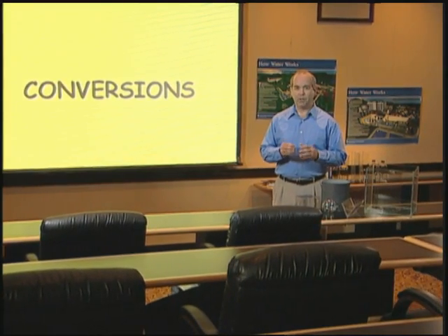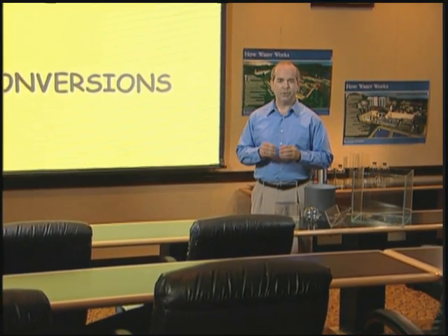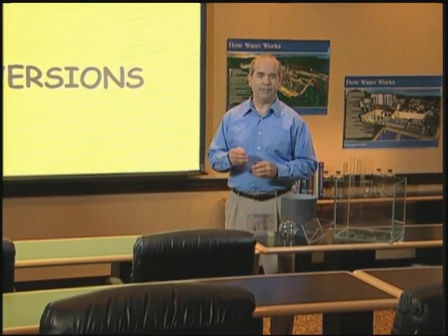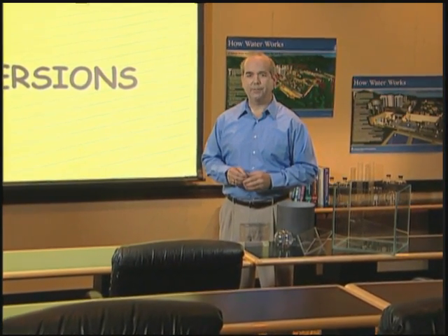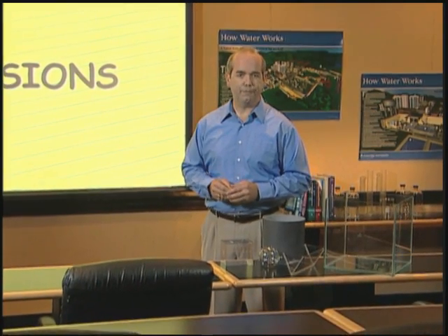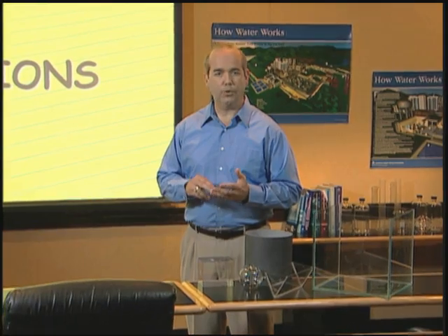Conversions are an integral part of calculating water plant formulas. To convert, you must know the number that relates the two units and whether to multiply or divide by that number. For example, in converting from feet to inches, you must know that in 1 foot there are 12 inches, and you need to know whether to multiply or divide the number of feet by 12.